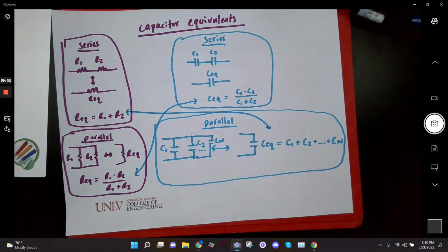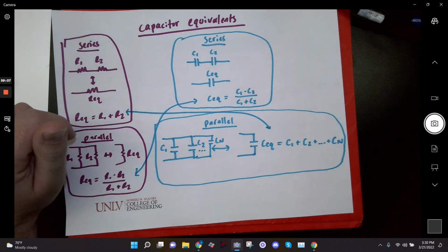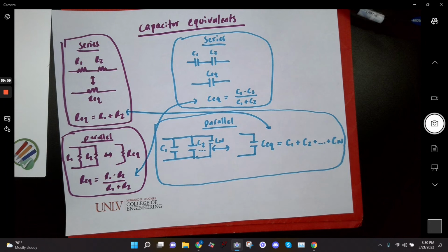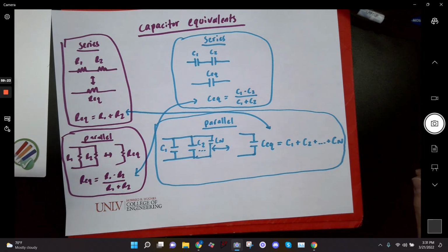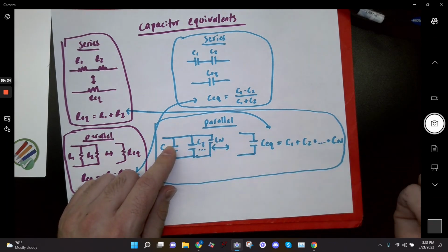Right? Yeah. Is it because capacitors are usually in parallel? Capacitors are usually in parallel because typically what you want is, let's say we only have 1 microfarad capacitors and we need a 10 microfarad capacitor. We just put 10 of them in parallel and now we have a 10 microfarad capacitor, right? Based on physics, I don't know why that's the way that they work, but that's just the way that they work. It's basically because you're just connecting all of these plates to each other, right?